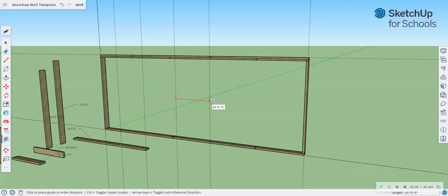The door opening on our reference drawing says that it's 3 feet wide, so I'm going to type 3 apostrophe, 3 feet. Once again, 3'6" is our next dimension. Notice also that that red arrow is always present when I pull my line over. Again, don't do this. So it went black. That's because it's on an angle. You don't want that.